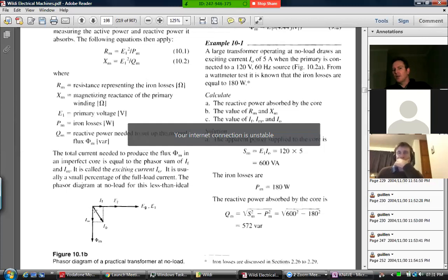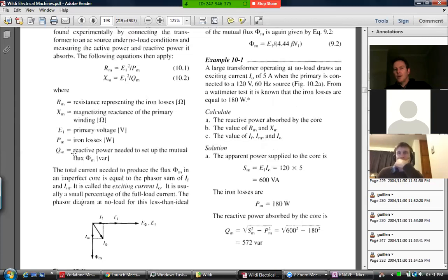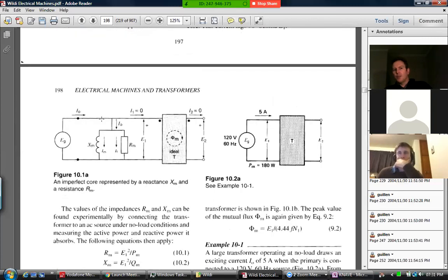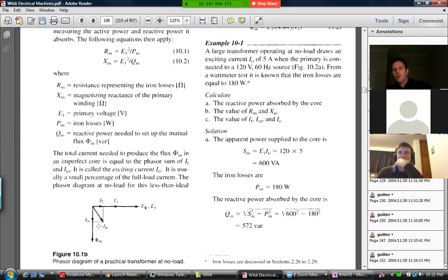There's a component that's going to be in phase because the resistor, when this voltage goes up here, the resistor current goes up instantaneously, whereas an inductor, if the voltage goes up, the current starts to build. You know what I mean? So this thing now gets pulled from the perpendicular only. You get a bit of component this way, so it starts to have a little bit of a less than 90 degrees effect.